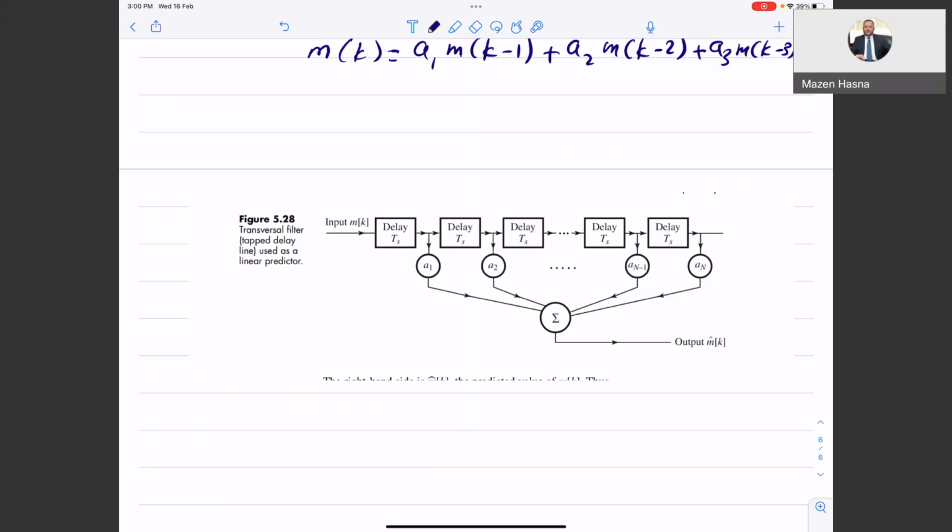You keep going, because the signal is changing. We will talk about delta. What's the size of the delta? Yes, it depends. There's also an adaptive delta, because if it's very small and the signal is moving fast, you will take time to track it. If it's large, sometimes you miss the details of the signal. So we'll talk about this probably at the beginning of next class.